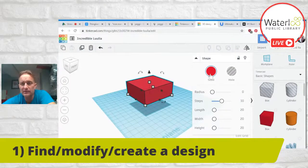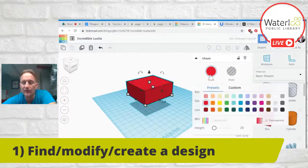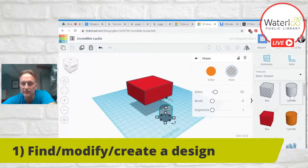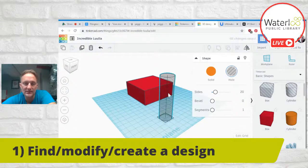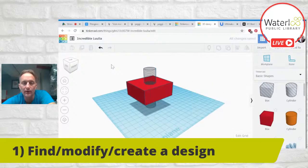You may notice here there are 2 major options, solid or hole. You could actually turn this into a hole, and it becomes kind of transparent, see-through. I'm going to leave it solid for now, but I'm going to show you how to work with a hole real quick. I'm going to take this cylinder and drag on the work plane. Now, this cylinder by default is already set up to be a hole. I'm going to make it bigger, and then I'm going to drag it into my rectangle here. There we go. So what we've just done is we've created a circular hole through the rectangle.